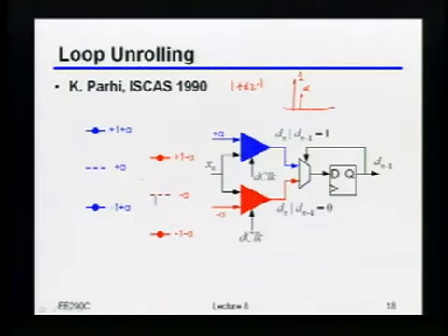The eye diagrams for these things tend to look funny, because there are 4 levels in the center of the eye, and then a whole bunch of transitions that can potentially happen on the edges. It turns out this has implications on how you do the clock and data recovery as well. We'll talk about that a little bit later. It also has implications on how you would even adapt the equalizer. We'll also talk about that later on today.